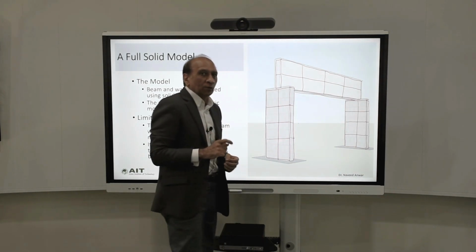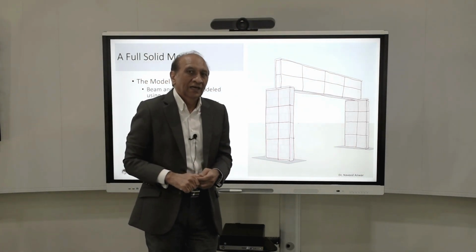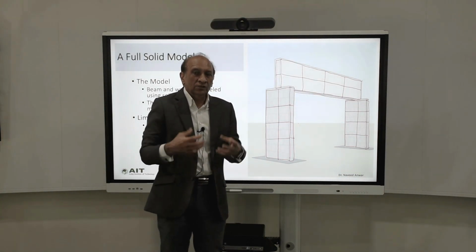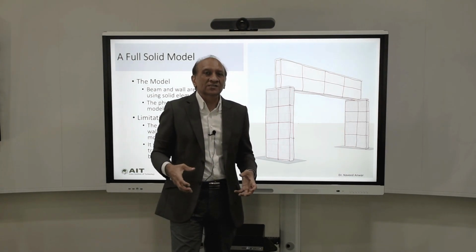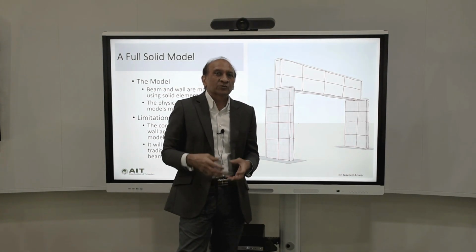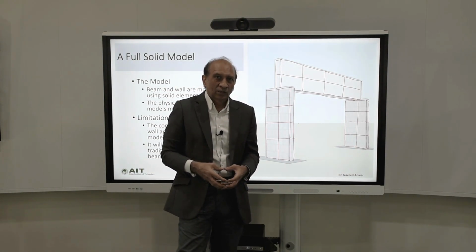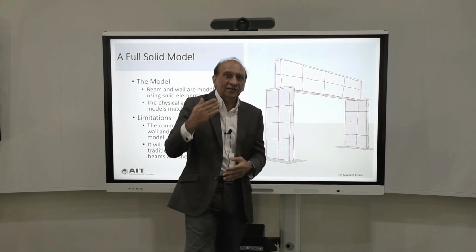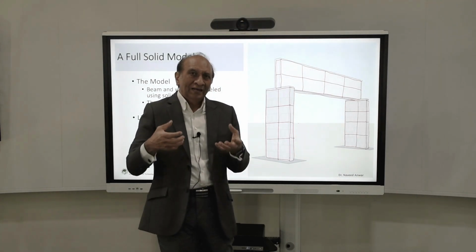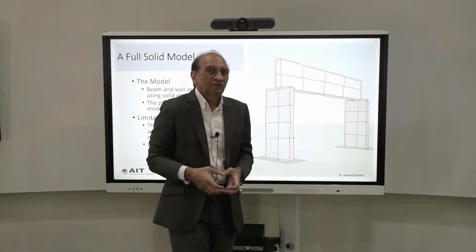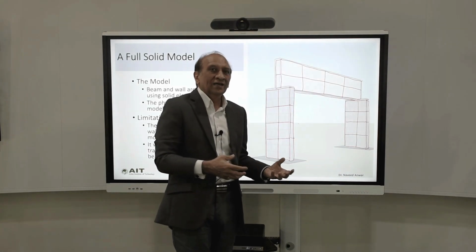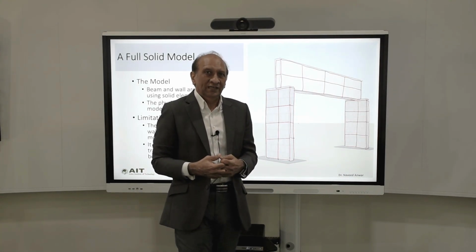And the other problem we have now created for ourselves is that it is not easy to calculate the bending moment in the beam anymore, because the solid element will not give us the bending moment and shear as we normally get from a frame element. Now we only get stresses, and those stresses will have to be integrated, converted back into bending moments and so on, and those stresses are not useful for reinforcement design directly. We will have to do a lot of processing to get a sense of what reinforcement we need.